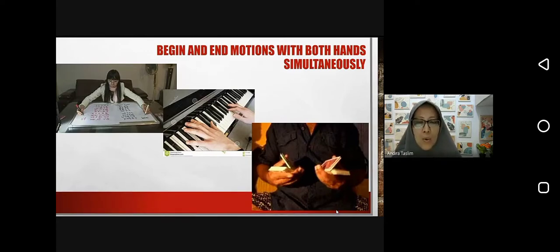So why do you keep the left hand to hold something? It is not efficient. It should be movable for both. So just keep your part in a jig, a fixture to hold it, and then both of your hands can be active, and the job will be finished faster. So it is the principle of motion for both hands.